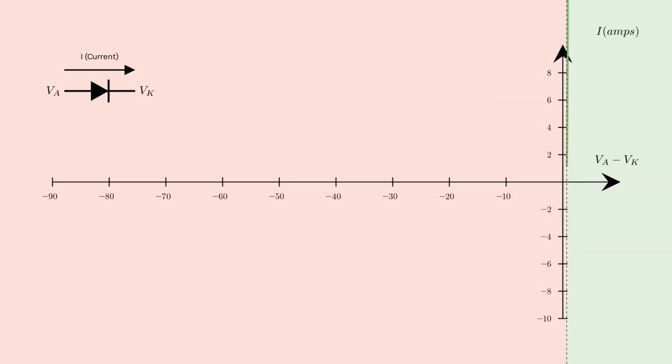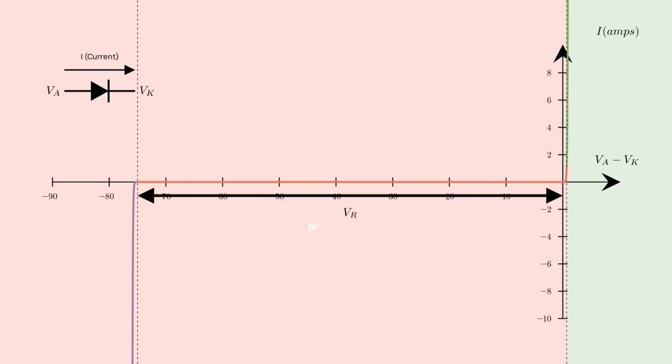There's a third mode going further to the left when the voltage difference becomes significant enough. There, charges get loose enough to jump the depletion zone like an insulator that breaks down. The voltage where this happens for each kind of diode is called the breakdown voltage. Depending on the diode model, it can be around tens or hundreds of volts. At the breakdown point, a lot of current can flow, and the plot bends sharply downwards.